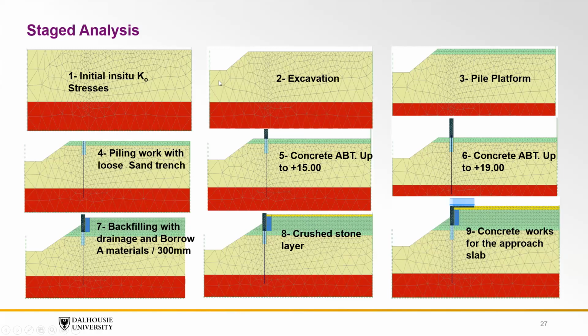So then we simulated the excavation. Then we placed the pile platform. Then we put our pile in sand. Then we continue with the whole construction sequence, till we have at the end our full abutment with the loads coming from the main structure.